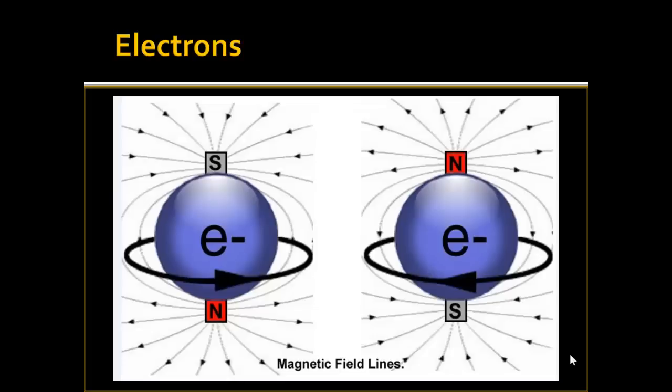That forces the molecules in the ferromagnetic material, called domains or dipoles, meaning two poles, it forces them all to line up in the same direction. And then when you remove the magnetic field created by the wire wrapped around it, not all of them go back into random order. So it's left with a net magnetic field, and now you have a permanent magnet.